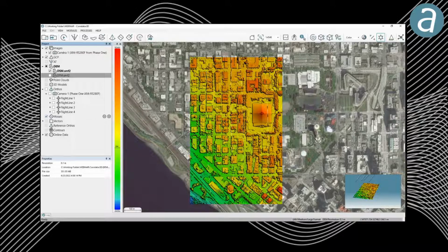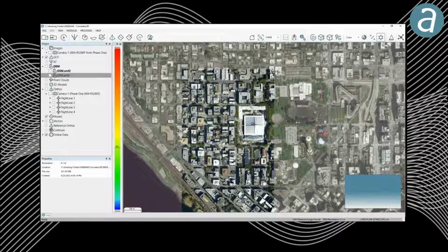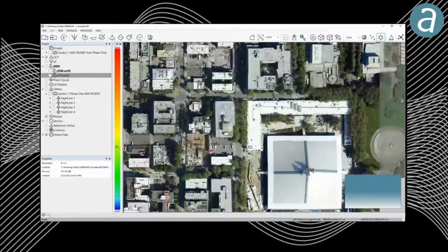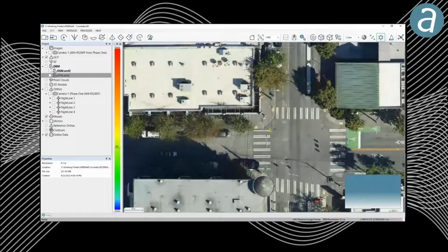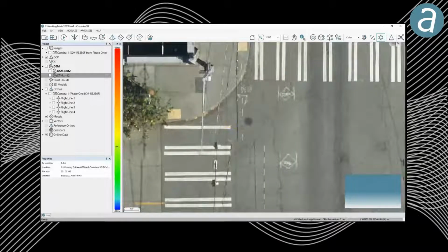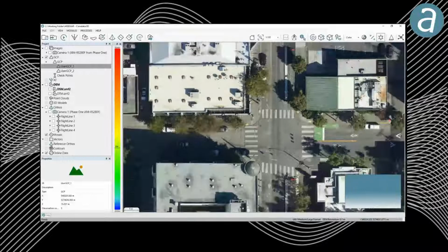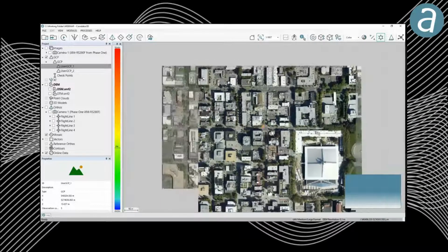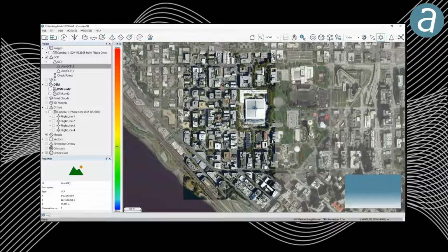Something I like to do when I complete my final mosaic and that I'm using GCPs is to zoom all the way to my GCP and then check if my mosaic is well sitting on the GCPs. So this one here is the side of the pedestrian path. I see that my mosaic is very well aligned with my ground control points. Yep. One last thing. What I discovered recently when we added this option to support the IIQ is that the color balancing is awesome.